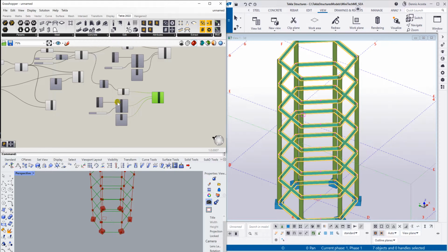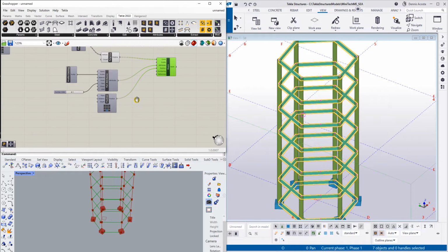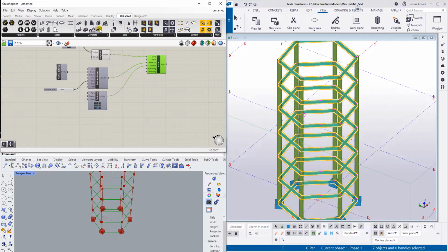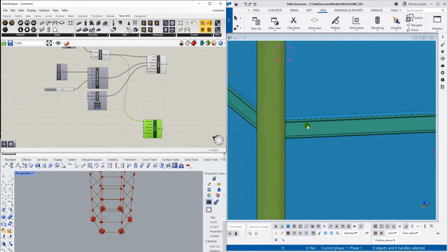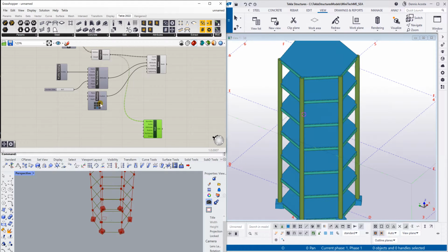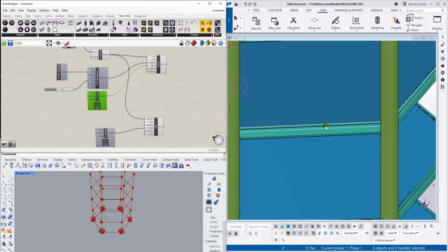So here, this one, slab. So there you go. So just simply click the polyline and boundary, and there you go. You have now the slab there. But of course, we can always change the profile for the slab. So the profile is also the thickness, but again here I can just simply change all. I can also put the position here. Position. There you go.